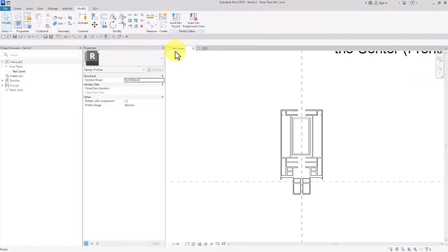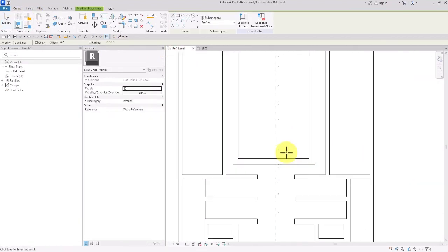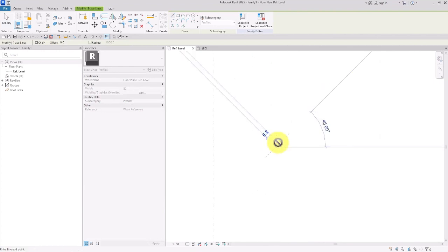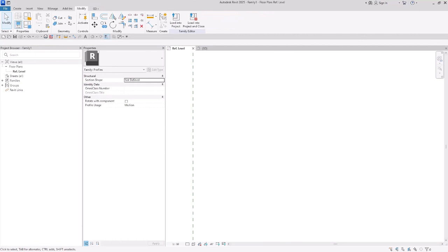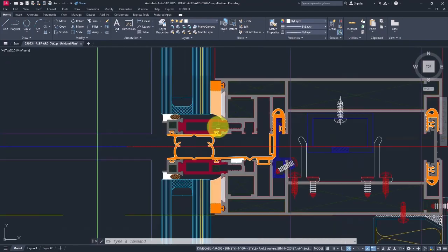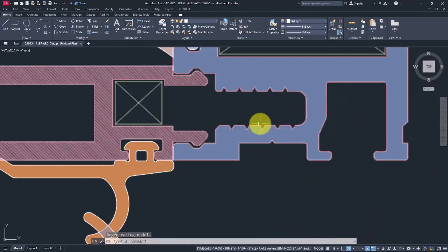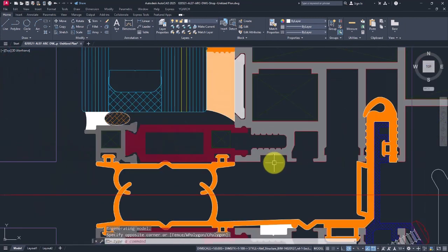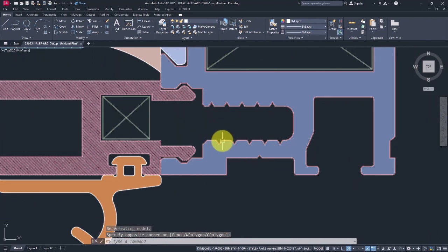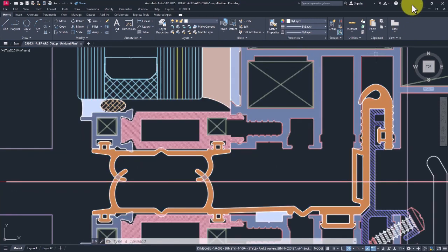For example, I said in Revit, if you wanted to draw a line, you cannot use a line weight less than 0.7 or 0.8 actually. This is why we cannot draw such detailed sketches in Revit yet. And we in fact use other software such as AutoCAD. And then we can, for example, simplify these sketches and convert these into, for example, a straight line, and then attach this detail as a two-dimensional, and then use them in Revit.